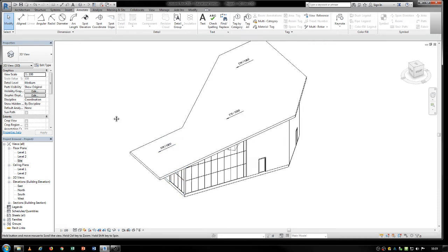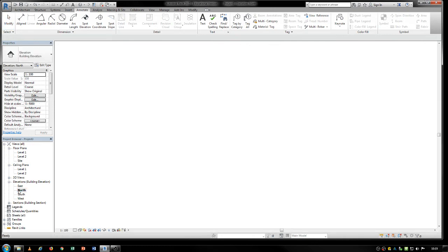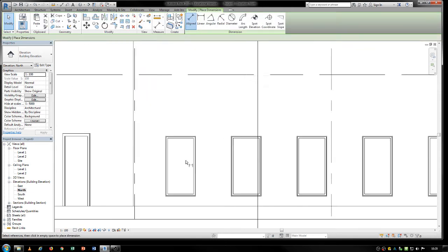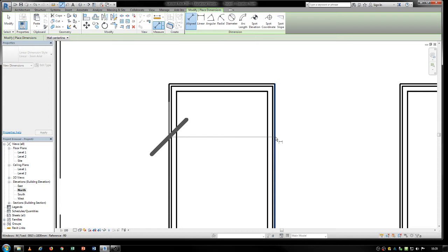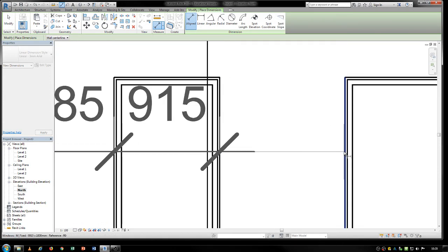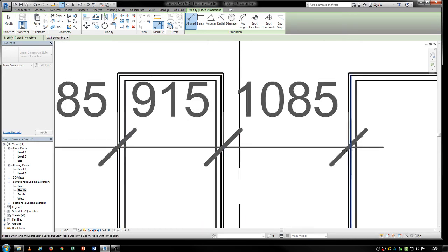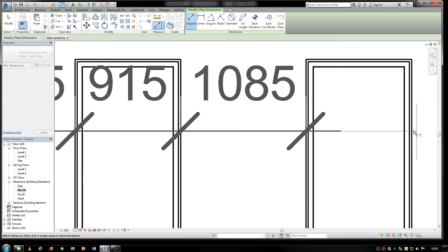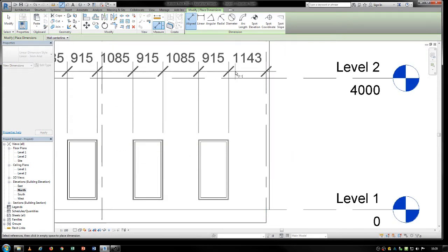And then this is very useful to show. So those are basically all the dimensions that you have, and you can just go in and use all of these in your elevations and sections as well. So again, going back here, it's very important to be aware of where it's turning blue and where you're measuring from and to, and then you will get all these dimensions. So from outside to outside to outside, or center to center to center, something that is logical and you can always follow. And then you would place it here.